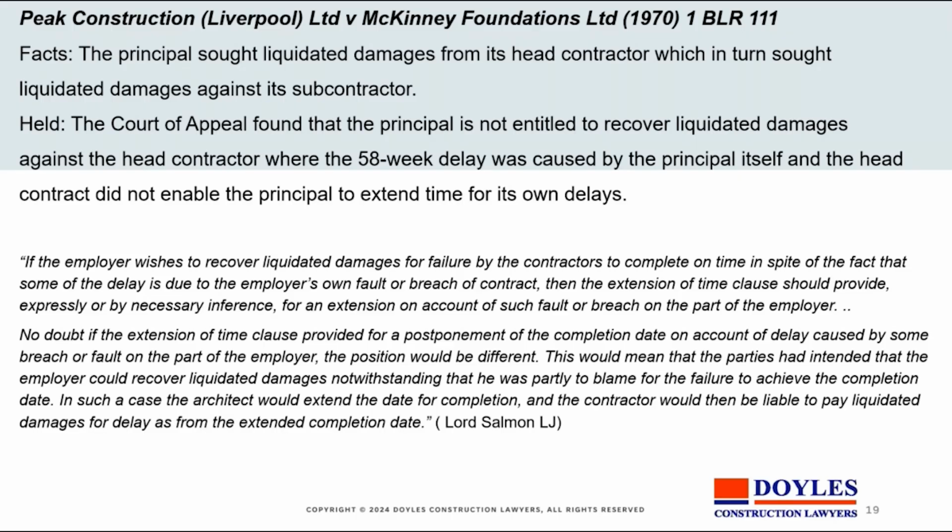It was found that the principal is not entitled to recover liquidated damages where the 58-week delay was caused by the principal itself, and the head contract did not entitle the principal to extend the time for its own delays. That's the important rider. So the situation is that if you don't have a clause that allows you to extend for your own delay, then your own delay will set aside the program if you cause delay.